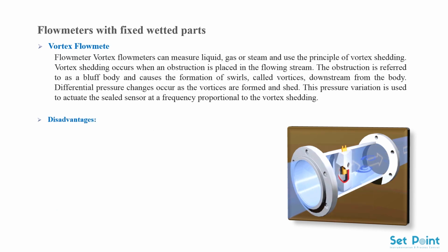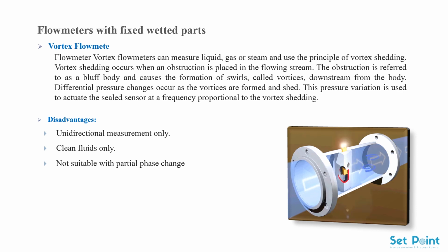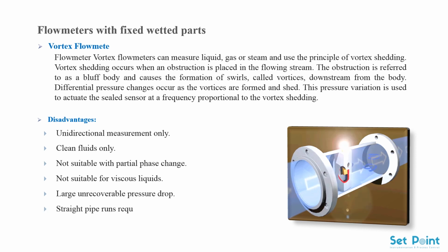Disadvantages. Unidirectional measurement only. Clean fluids only. Not suitable with partial phase change. Not suitable for viscous liquids. Large unrecoverable pressure drop. Straight pipe runs required for installation.